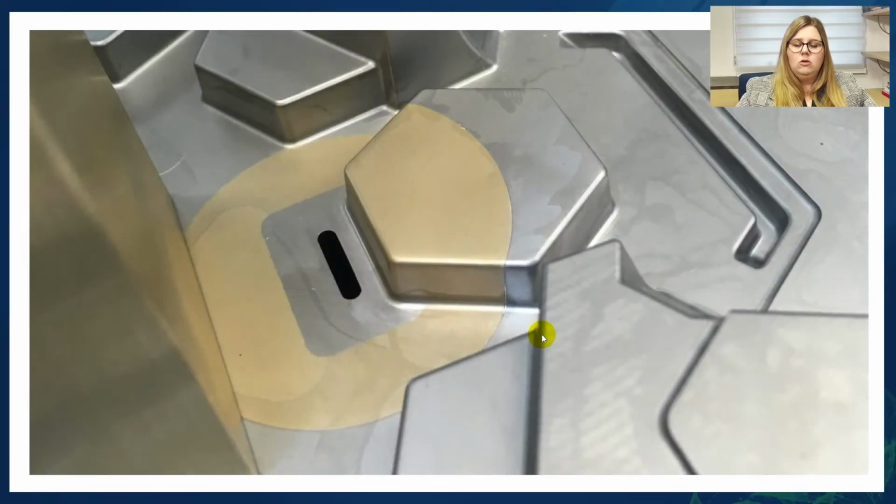When you have different components where there is a lot of wear in a certain area, you can deliberately weld on harder materials here, or you can do the opposite. When the mating part is easy to repair, you can print softer material here to make sure that wear takes place here and not on the part where repairs are more difficult. You can see an example here.